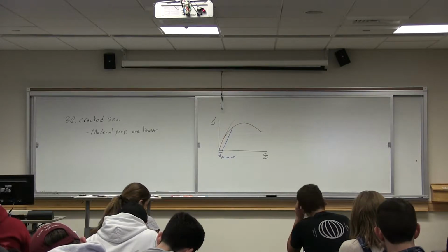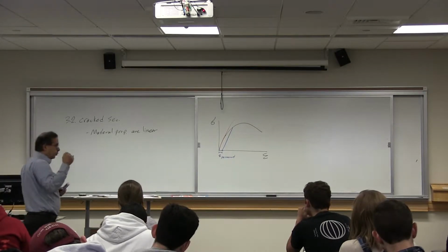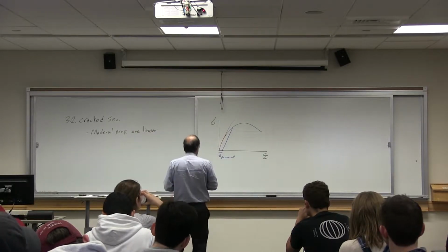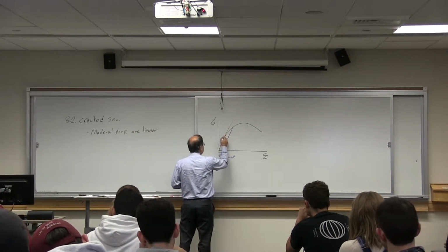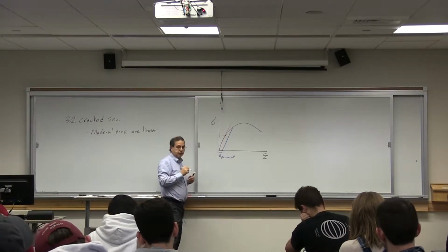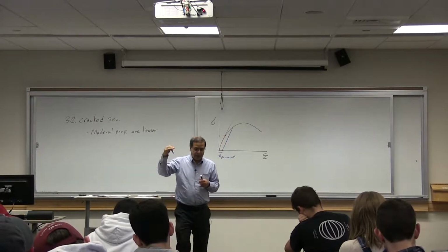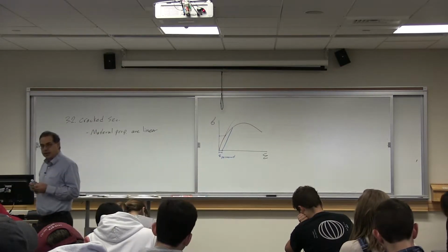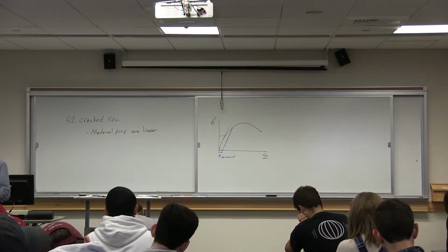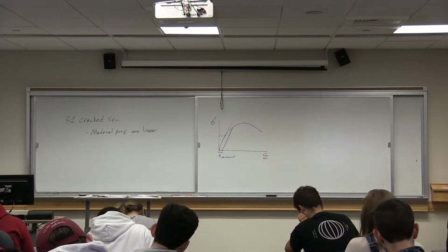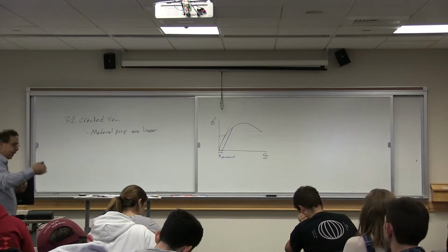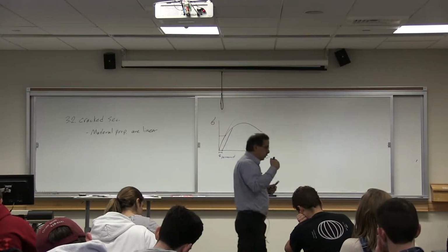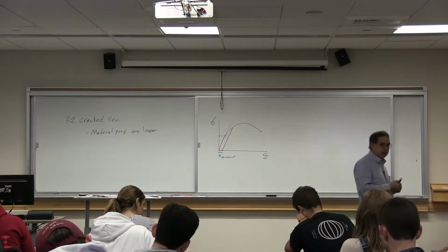And the general idea is it would be a good approach to limit the amount of stress in concrete up to the point that concrete is almost linear. That's a good approach. Why? Because when you apply the loads every day, you load, unload, you don't keep adding damage to the system.